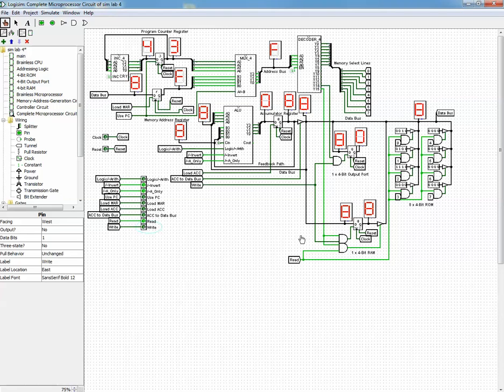Okay, so right now this has activated this buffer, because this AND gate is activated through the 15 and through the read. So right now this buffer is activated. So now the 8 passes from this memory unit, the output of the memory unit, to the data bus. And the data bus, if you track it, you find that it will carry the 8 to the input of the arithmetic logic unit, so that you can do whatever you want, either invert it or do arithmetic or logic or whatever you want to do. Okay.